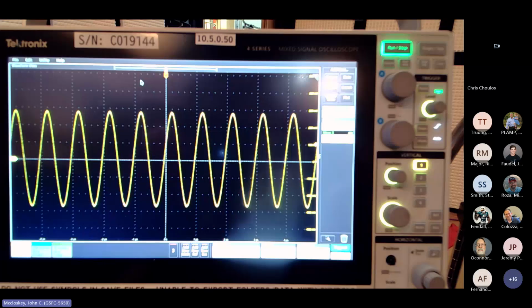So pretty much throughout the whole process of working with CS114, you are not working directly into a 50 ohm load. So to make sense of the levels you're seeing, you have to think of it as having twice what I'll call the advertised signal level. If your signal generator is telling you 100 millivolts RMS, you need to double that to be your true source potential going through a 50 ohm source impedance.